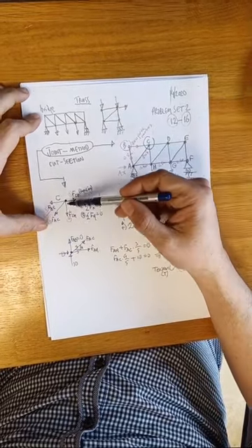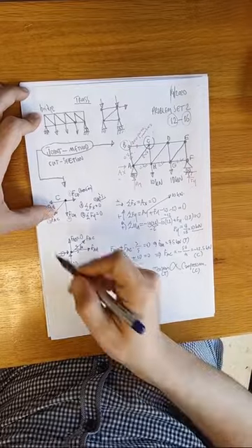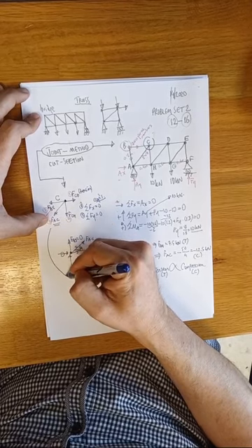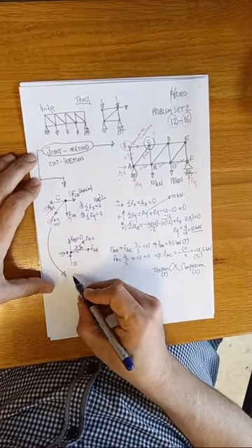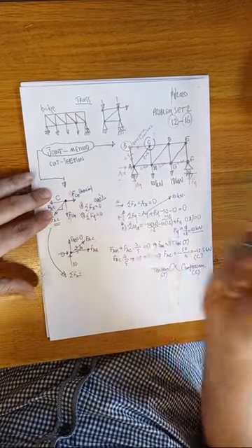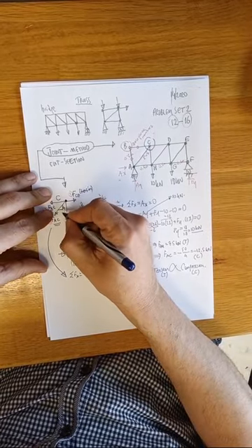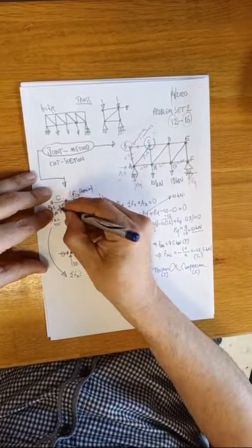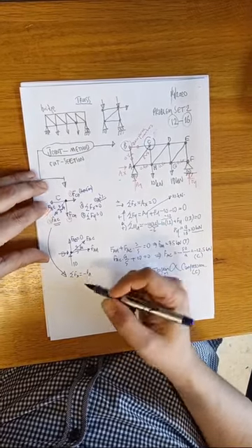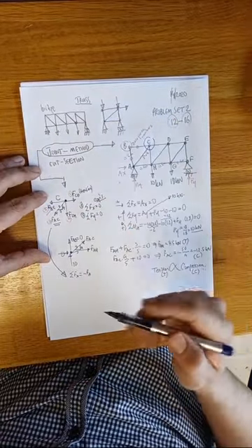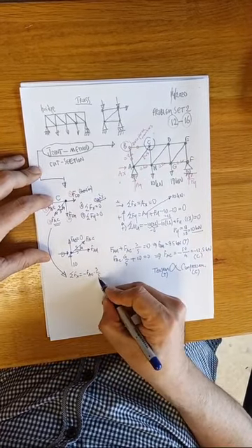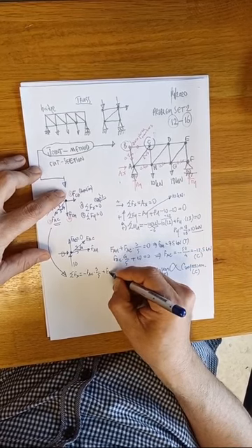Now maybe you can pass now to the C joint. Now we know FAC here, if you know FAC, then you can find now FCD and FCH. Now I'm passing to the C point. Let's write the forces in X direction. Okay, what is this FAC? So let's write first this triangle. It would be very useful for you. Do it every time, 3, 4 and 5. It would be very easy now. FAC, but in minus direction, because the horizontal component, as you see, is in minus direction. FAC times, what is this? 3 divided by 5. The other one is FCD, should be 0.